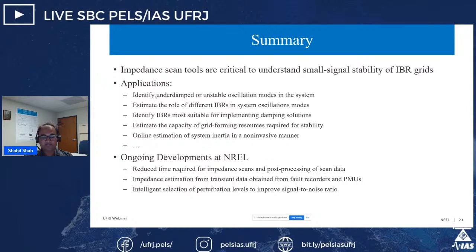For high frequencies, it's easy because if the oscillation modes that I'm seeing are occurring at a couple hundred hertz, like 200 hertz, then I can have a really small FFT window, right? Like a fraction of a millisecond or a few milliseconds. So high frequency scans are easy, but most oscillation modes that are going to be system wide are going to be low frequency.